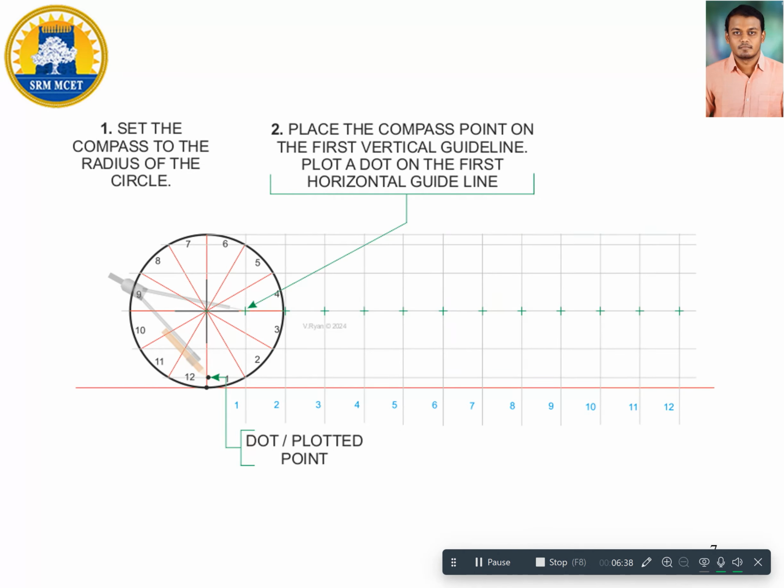The next step is to draw points exactly parallel to the baseline points which we have divided earlier. Earlier we divided the baseline into 12 equal divisions using the dimensions of the sector with a divider. Now, placing our scale vertically and perpendicular to the baseline, I am going to mark 12 points onto the central line originating from this central point.